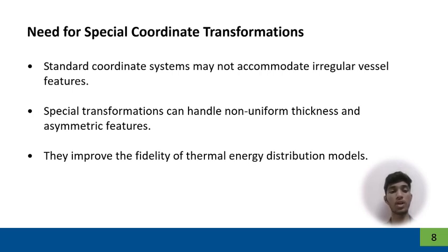Standard coordinates are not enough when vessel walls have non-uniform thickness, there are asymmetric features, or the geometry is irregular or complex. Special transformations allow us to fit the coordinate system exactly to the physical shape, making thermal simulations more accurate and reliable.